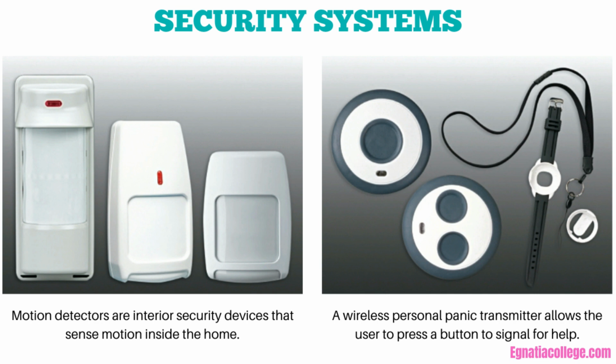Heat detectors and smoke alarms are generally connected in parallel because all of these devices will close the circuit to the security master control unit, setting off the alarms. Fire detectors are available for series connection for use in security systems that require normally closed contacts for circuit operation.